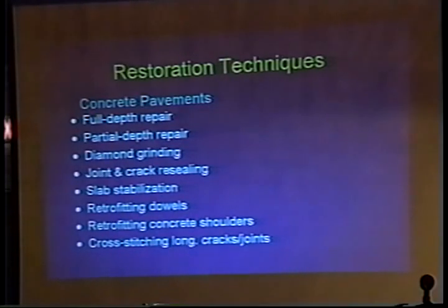These restoration techniques that I'm talking about are actually not that intrusive when you take a look at what you're actually gaining from that. Full depth repair does call for a cutout and full replacement of a section of the concrete pavement, or multiple sections that are deteriorated. So you have to take into consideration how you're going to handle maintenance of traffic. With some of the fast track methods that we have available, and I think Jim will probably get into this in a little more detail, we can minimize the disruption to traffic better than we ever have before.